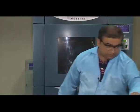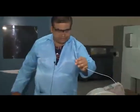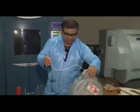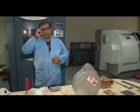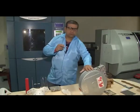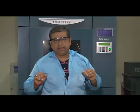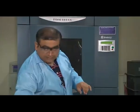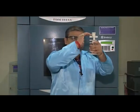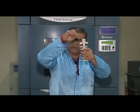The basic raw material for this process comes as a roll. You can see this is a wire roll, and this is what the basic raw material comes as. This wire is fed from a very small nozzle which is able to move in an XY plane with the coordinate position information which it would have from the CAD file. Supposing now there is a sectioned layer of such a complex part, I showed you a part can be as complex as this. So probably I have made a small section of this somewhere here, and I am seeing what are the coordinates of that particular section and defining the tool path.